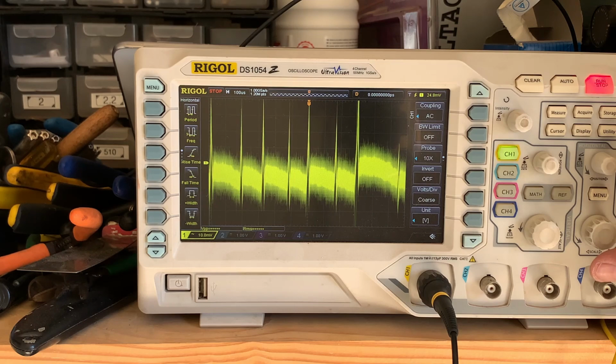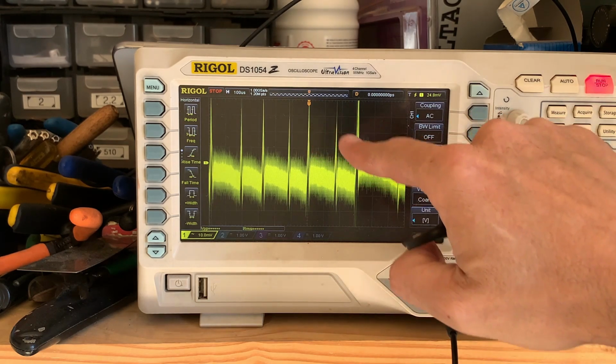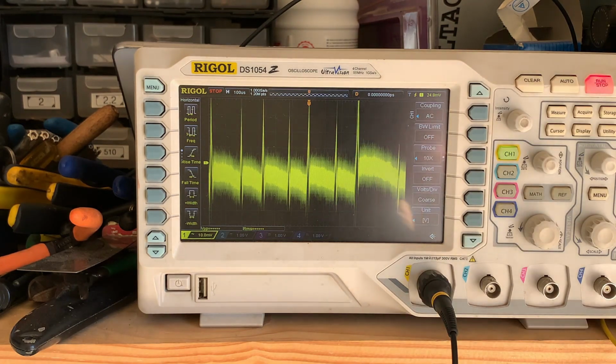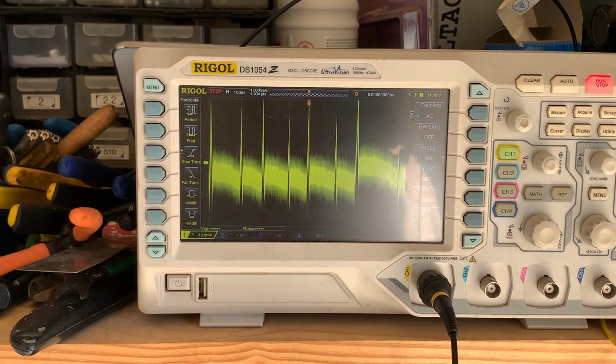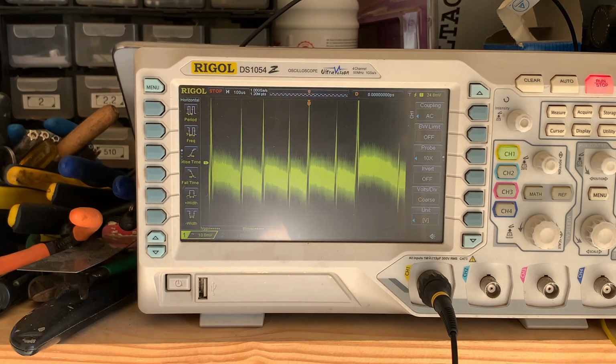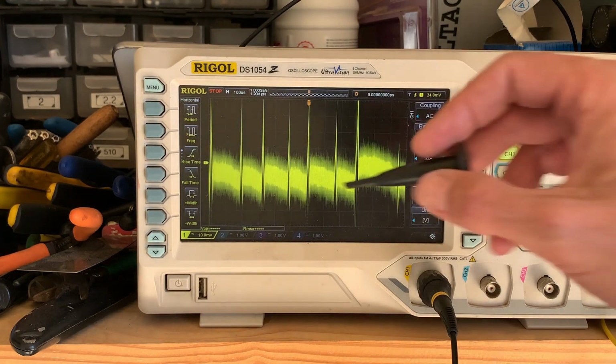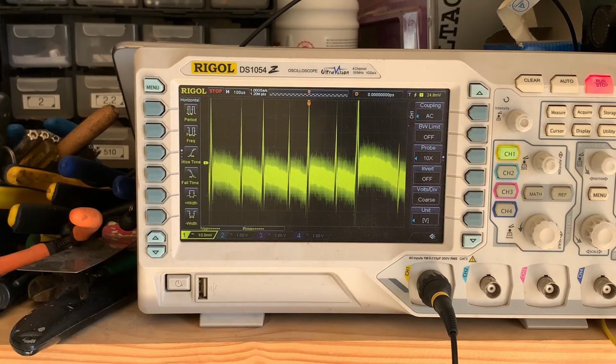Okay, and this is, let's say, 200 milli, sorry, I lie, microseconds. So let's say 200 microseconds. So of course it's at 5 kilohertz that it's happening, 5,000 times a second. So you can see, even without any feedback, the op-amp is doing what it can to make the two inputs meet. Of course I could probe it better.